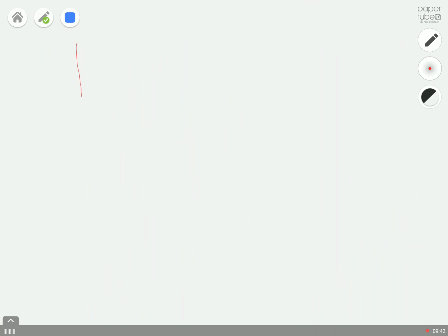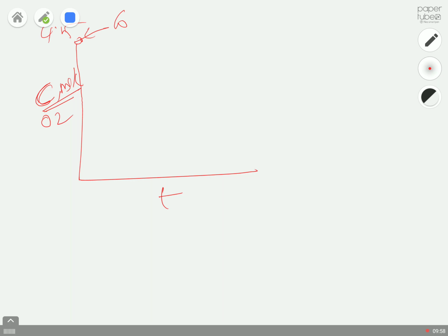So you plot time versus O2 concentration. You can call it C, concentration of oxygen expressed in milligrams per liter. It will start from 4.5, that's your initial C0 value. You will get something like that. Somewhere it cuts at 0 here, around 7 minutes, I think.